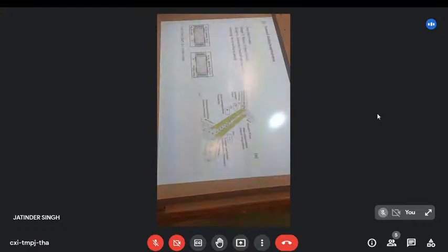We then change to a new electrode here. You can see that we've got a little gap here between the two different electrodes going to the second dimension. First dimension, second dimension. Different potential difference, different AC potential difference applied. Now a little bit more tuned towards one particle or another. So you can see here that the green particles really want to move towards the other electrodes. The red particles, not as much. Because the green particles feel a much stronger dielectrophoretic force than the red ones, they get pulled across the middle line. And once pulled across the middle line, they end up in the acceptor channel here.